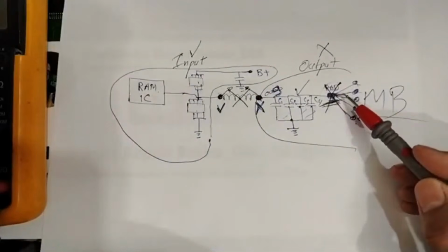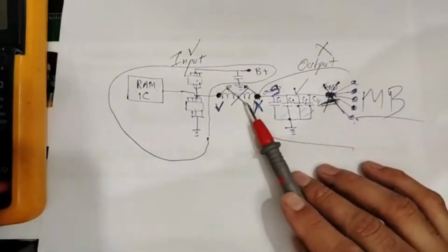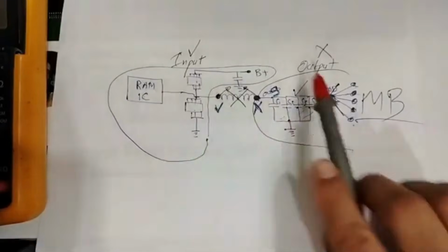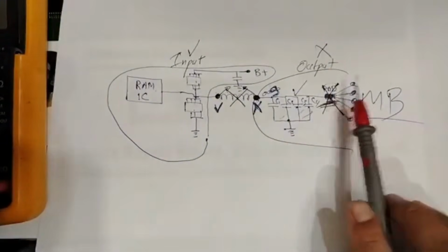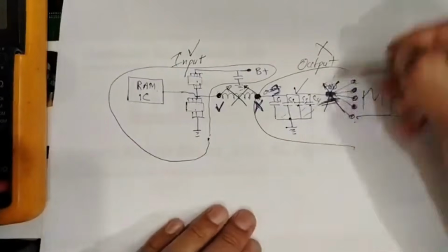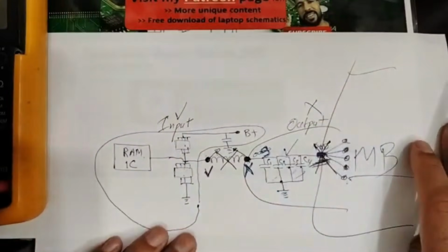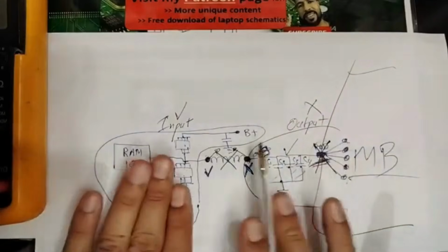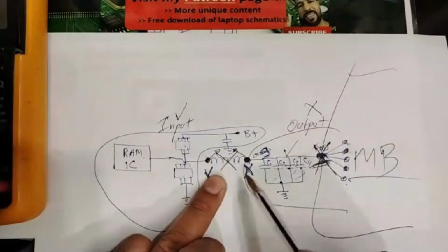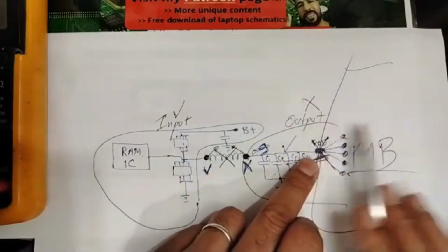Of course, you can remove the pad first, but why did I remove the inductor? Because the majority of shorts are in the circuits. Here we have outside the circuit. From the pad to this side, this is outside the circuit. We have short inside the circuit. We find the short inside the circuit, so we always begin with the short here. But in this case, no. The short is outside.